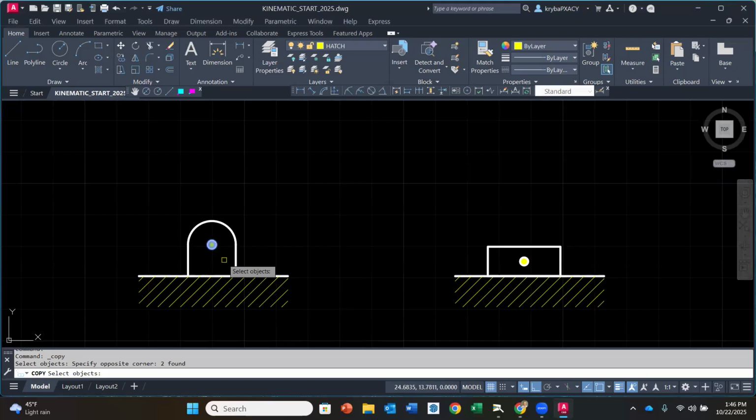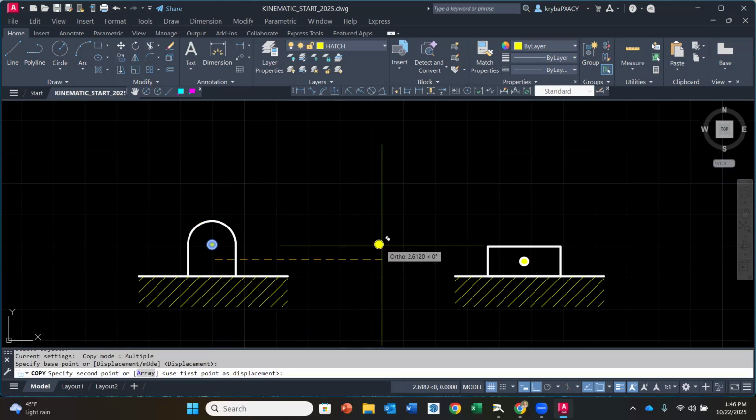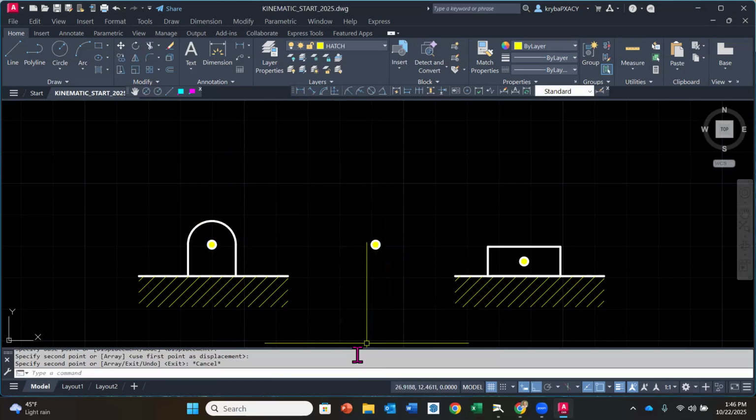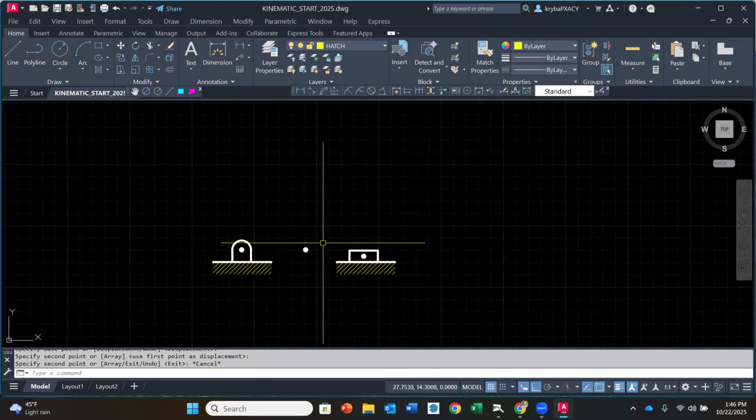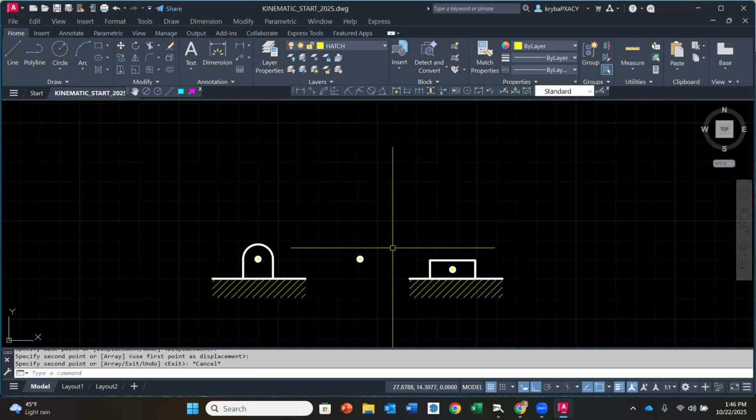Okay, so you want to put a window around that, hit enter, and then I just want to move it from there, maybe into the middle here, somewhere else. This way now I have a pin joint that I don't have to keep drawing again and again. So each one of the elements I want here is a frame, a pin joint, and a slider.